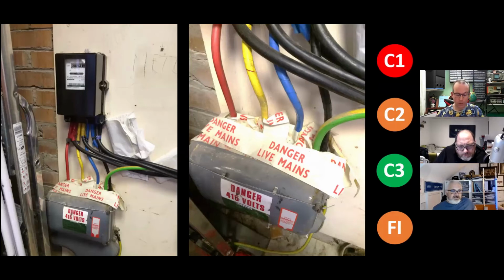But that also looks like it's an asbestos one as well. This might be, oh no, actually no, sorry, that's not asbestos. My apologies. That's the old electricity board sticker on that. Oh blimey, don't see many of them around anymore. And then some funky seals. So what would we code that as? What's the tape about? It's falling off on tails. Is the blue cable actually white? No, it's just the way the tape's lying against it, but good spot.